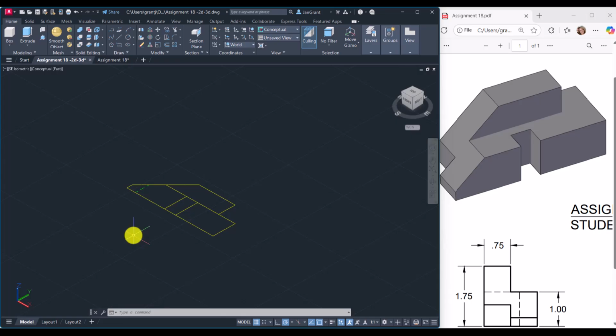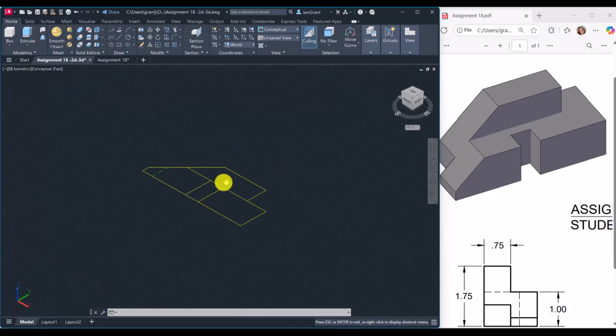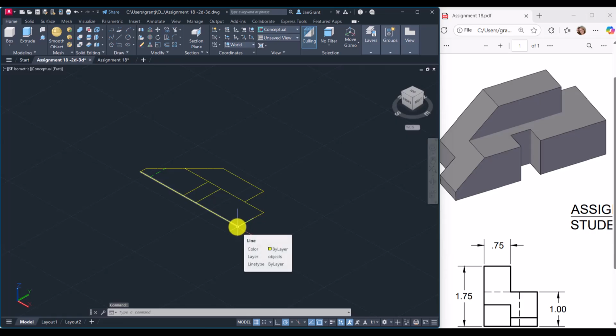All right. Yeah, we might as well use press pull right now as we're working with it. What we're doing is this piece right here is the middle. I think you would clearly see it better if we rotated this up like 90 degrees. So let's rotate it, 3D model, rotate, 3D rotate. We're going to rotate it from this corner just up 90 degrees.